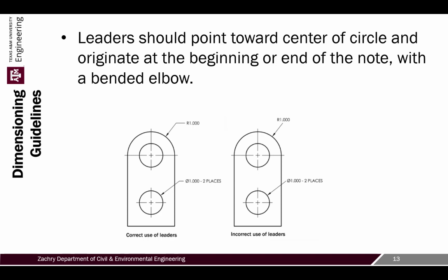When you're creating the leaders, remember leaders are what we're going to be using for curves and holes and things like that. That leader should actually touch what you're identifying, but it should point towards the center of that arc. So in this case, you'll notice that it's pointing right towards the center of my circle. So you want to make sure that you do that.